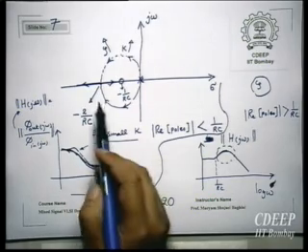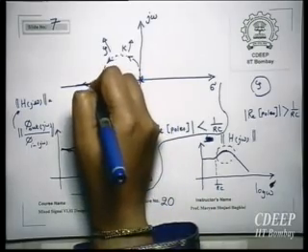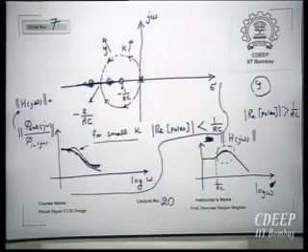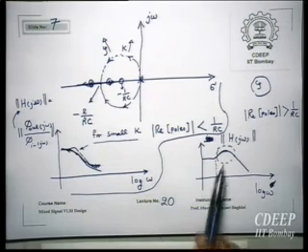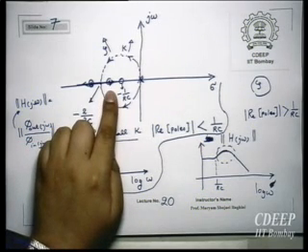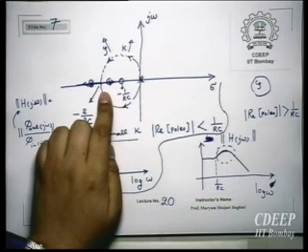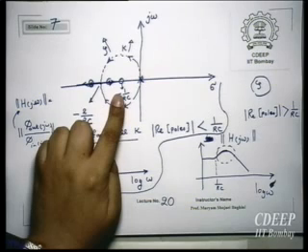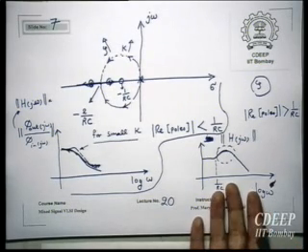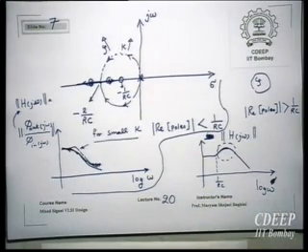No, see, if you make both poles real, for example, one pole will be here now. I show it by this symbol. One pole, for example, will be here, and 1 0. No, it will be good because you don't have peaking anymore. Effectively, this pole goes to the left, right? Therefore, this pole will be the dominant pole. So you have one pole, 1 0, and the pole is on the left. Therefore, anyway, you will see the effect of the 0 first. Okay, yeah, his point is that we will see the effect of the 0 first. Anyway, this peaking will be there. But therefore, this is not good with respect to jitter performance. It is good with respect to stability.